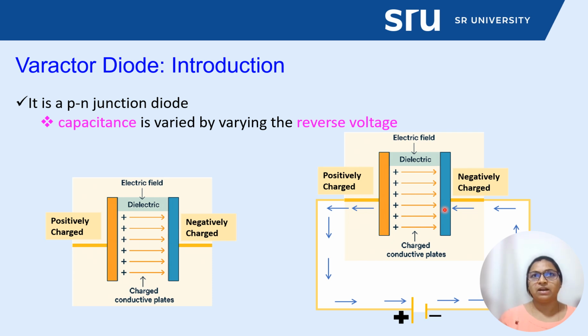As a result, a large number of electrons build up on the right side of the plate. Thus, the right side of the plate becomes the negatively charged electrode. The dielectric blocks the flow of charge carriers, that means free electrons, but allows electric forces exerted by the negatively charged electrode.